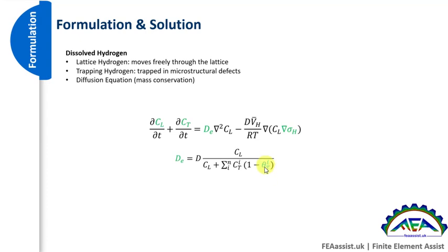After computing the effective D_E, we can have this number, D_E over f, the loading frequency, and we can decide safe and unsafe fatigue regimes by this parameter. But if we want to compute trapping density, we have a very well-known equation, the Oriani relation.